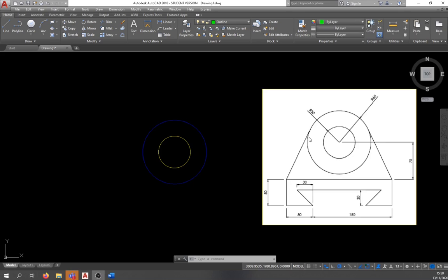In this case, we want to go down to here, but we don't know how far we have to go down and what distance this is. We know what this complete distance is, so it's over 200 long. If it's 200 wide at the base, then we know the midpoint is going to be 100. So what can we do with that? Well, if you look at this dimension here, we know that from the center point of the circle down to this line is 70 units. And then from this line down to the base, it's going to be 50 units. And we know the center of the base is going to be 200 here.